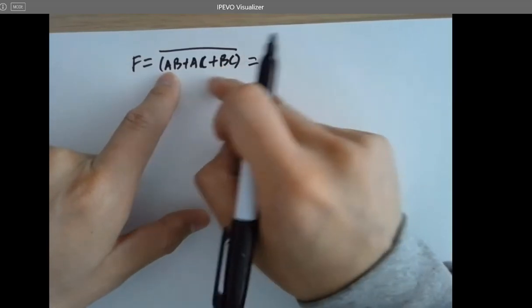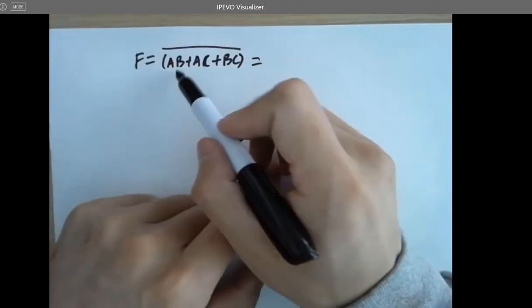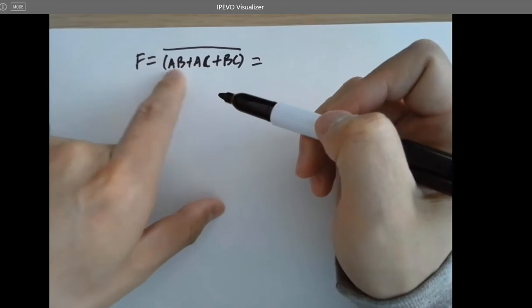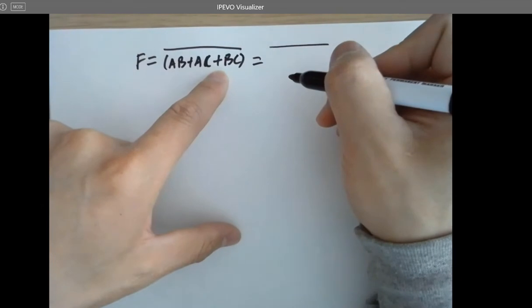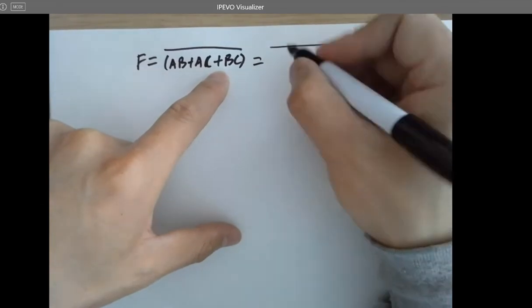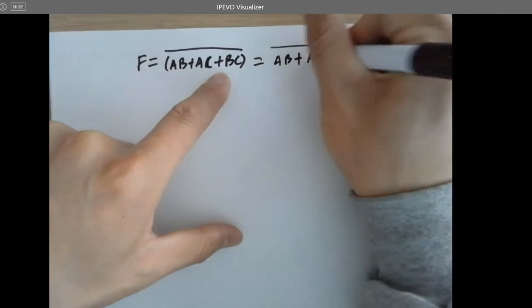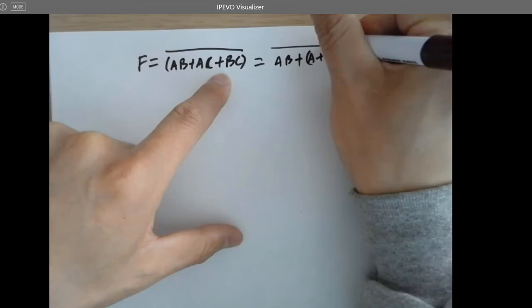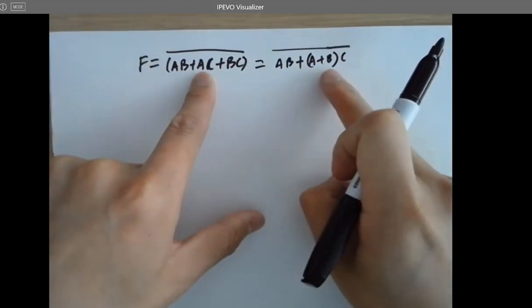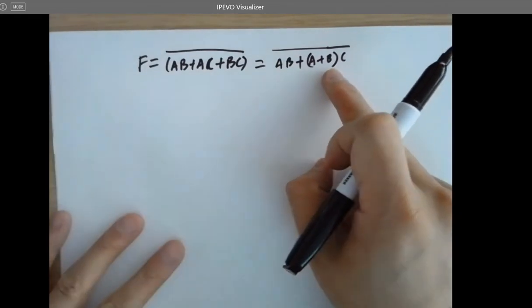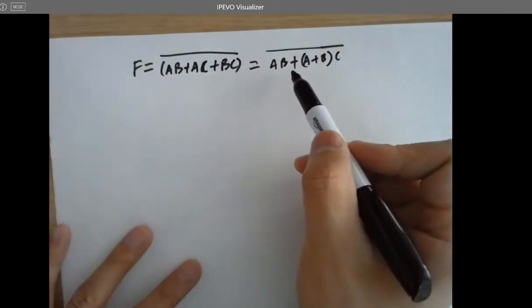That looks like too many in series, too long for the structure on the top. But you can see there are common terms for these ones, so you can combine them together to make it look simpler. It can be simplified. It's AB or (A or B) and C. I just combine these two in here. And then you can start drawing the PMOS and NMOSes.